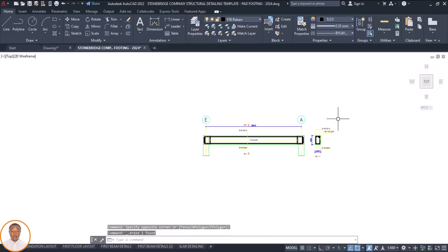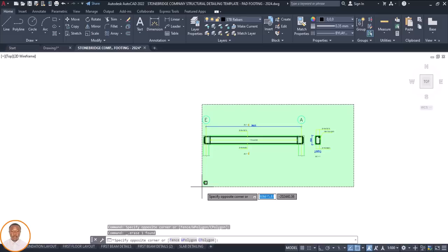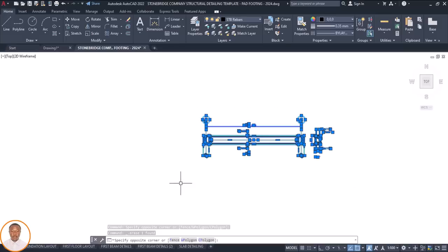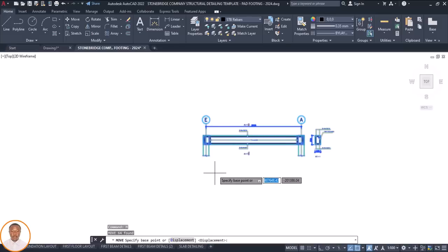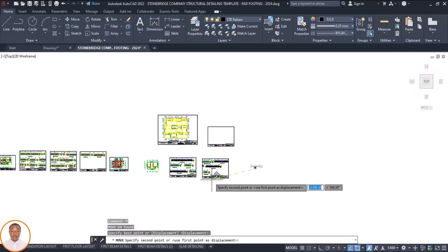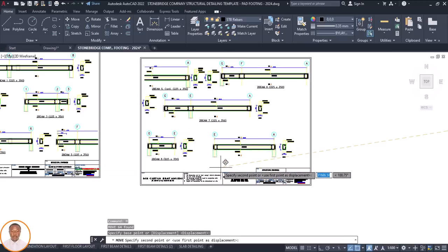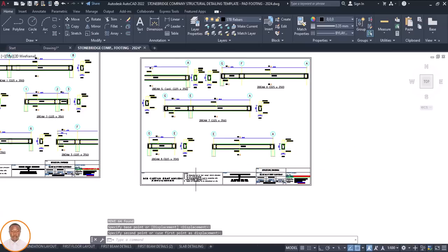I'll just come to this last one. Okay, let me see. Come up, click on this one, select it rather, and then M, enter. Is that okay? M, enter, move it. Okay, I'll come here and put it somewhere here. Perfect. So that is that, and then click on this one and then CP, enter, then come here and put it on this place.